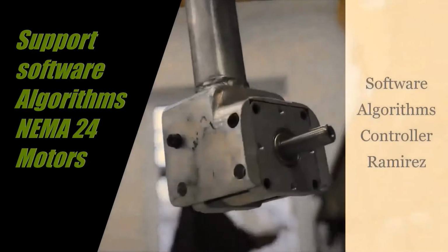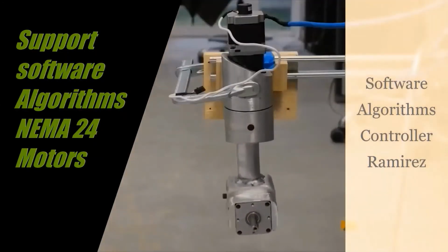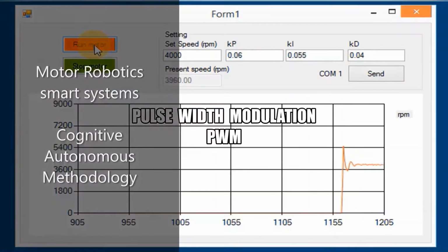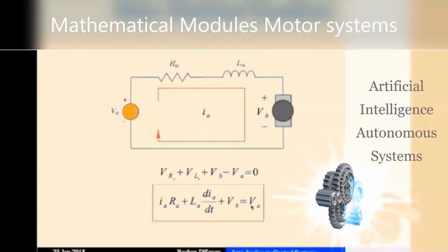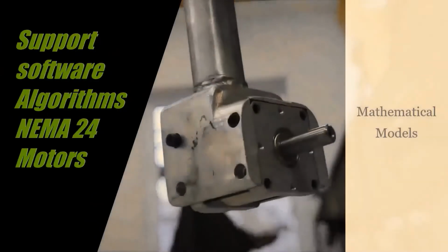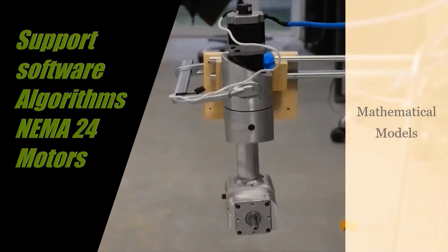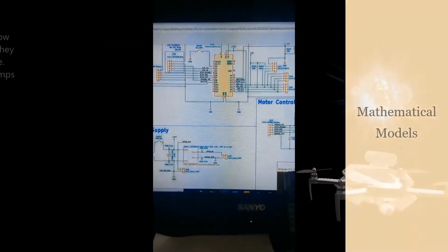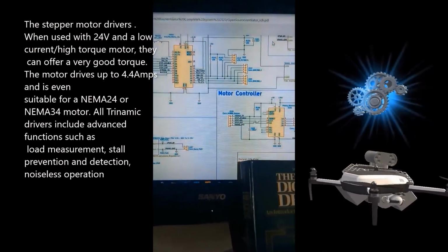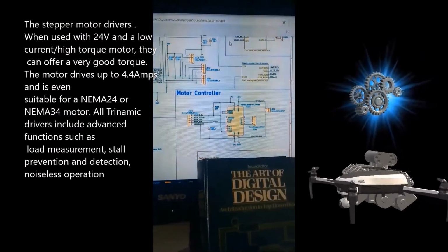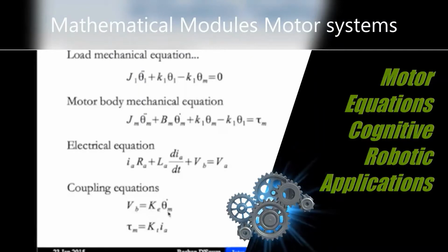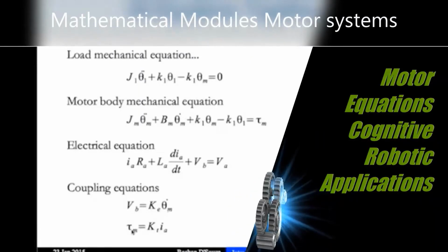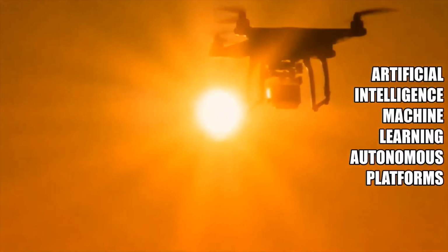The torque, which is the output torque of the electrical motor, depends on the intensity of the rotor and stator magnetic field and on their phase relationship. The angle theta between the two magnetic fields is named load angle, and the maximum output torque and the maximum efficiency is obtained when the load angle is 90 degrees.